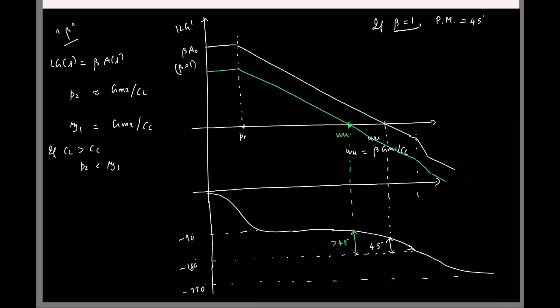So the takeaway is, for these Miller OTAs, what can you comment about the phase response? In general, if you look at the phase response, it's monotonically reducing, right? For Miller OTAs, you have continuously, monotonically reducing phase. So beta equal to 1 is the worst case feedback factor.